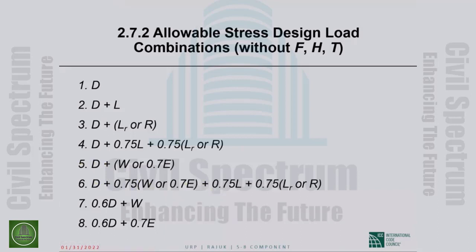The only other thing I might say is we typically refer to these as additive load combinations. Dead load causes bending moment in the same direction as the bending moment caused by wind or earthquake. Here, these are counteractive load combinations. Dead loads cause negative bending moment. Wind causes positive bending moment. So the dead load counteracts the bending moment due to wind or due to earthquake.